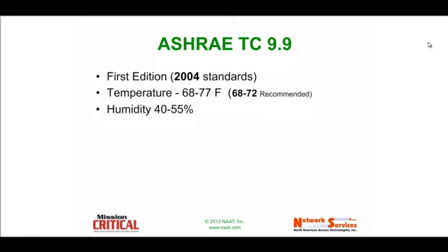as tightly as possible. The industry has really lived with that for many, many years, and in fact, obviously predates that, going back to the days of the mainframe. And as a result, we've pretty much fixated on that 70-degree, 50% humidity number for the last 30 or 40 years. Equipment has changed radically since the days of the mainframe and paper tape and punch cards and such, and frankly, a lot of the humidity specs in particular relate back to when we used to process tons and tons of paper, both for punch cards for the input and reams of paper for green bar printouts that used to all reside within the same data center space.